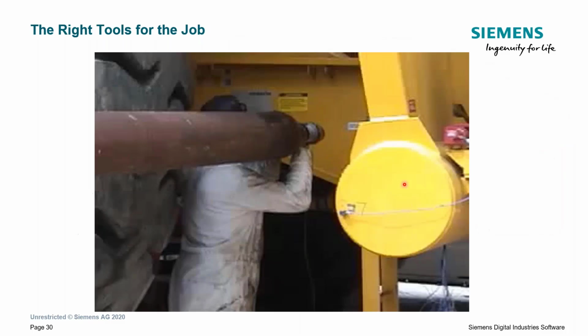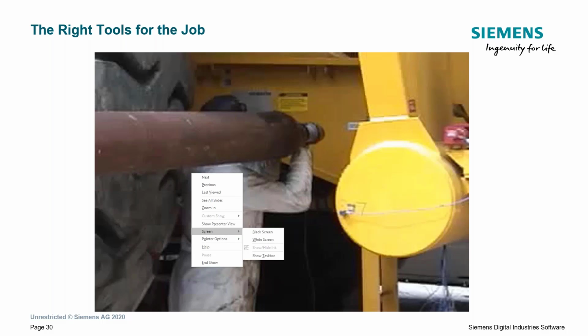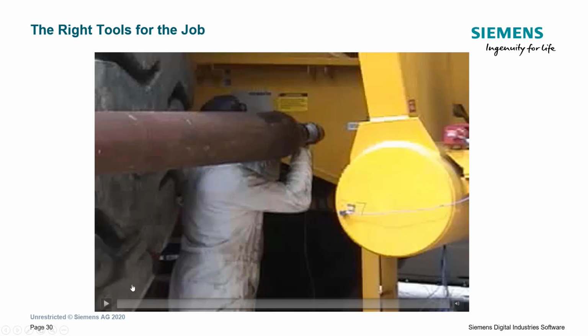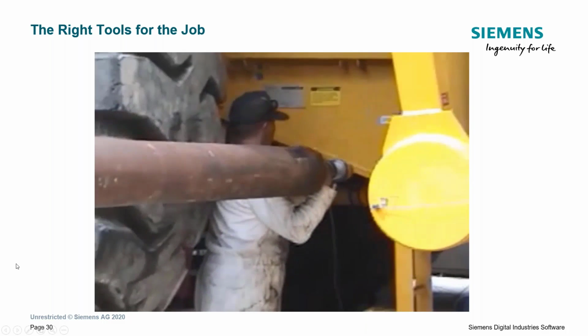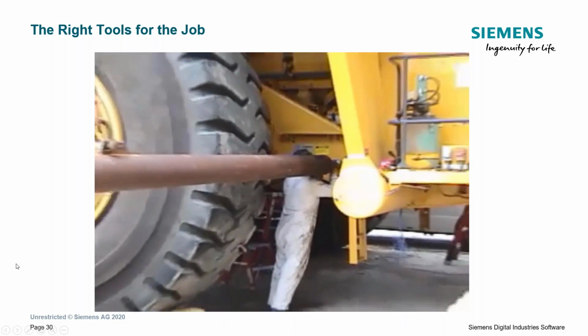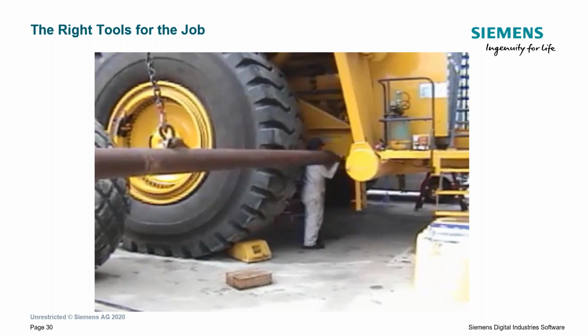If I want to stick with hammer testing, I can still use a hammer, but like we talked about before, we're going to want the appropriate hammer for the job. And in this case, we have this hammer. We're looking at low frequency for this large object. We're going to need a big hammer.